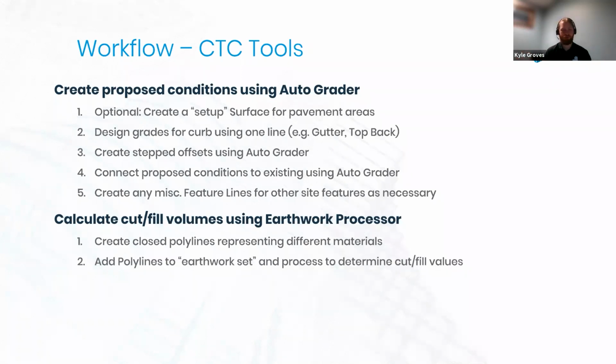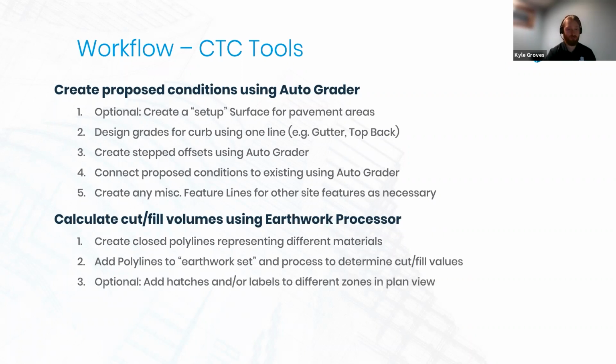And then same thing for our proposed conditions. We'll take these polylines and we'll add them to something we're calling an earthwork set, and then it'll go through and process those. The tool will create the necessary intermediate surfaces, and eventually we'll end up with one final volume surface that'll report us our cut and fill values.